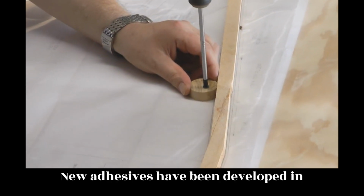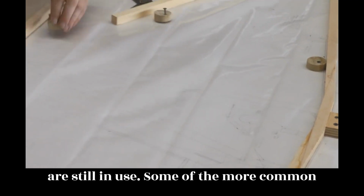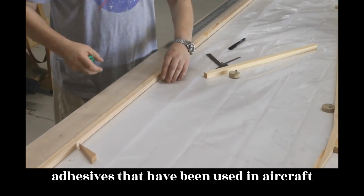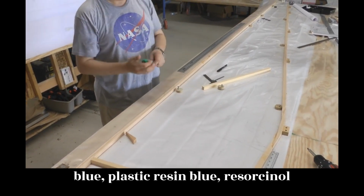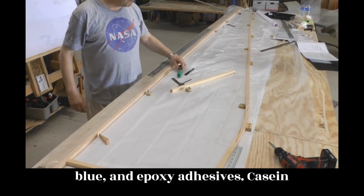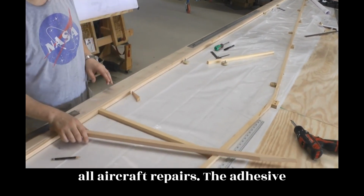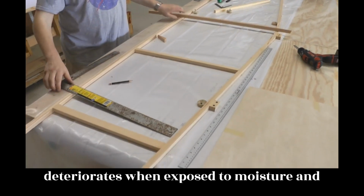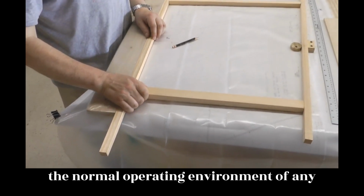New adhesives have been developed in recent years, and some of the older ones are still in use. Some of the more common adhesives that have been used in aircraft construction and repair include casein glue, plastic resin glue, resorcinol glue, and epoxy adhesives. Casein glue should be considered obsolete for all aircraft repairs. The adhesive deteriorates when exposed to moisture and temperature variations that are part of the normal operating environment of any aircraft.